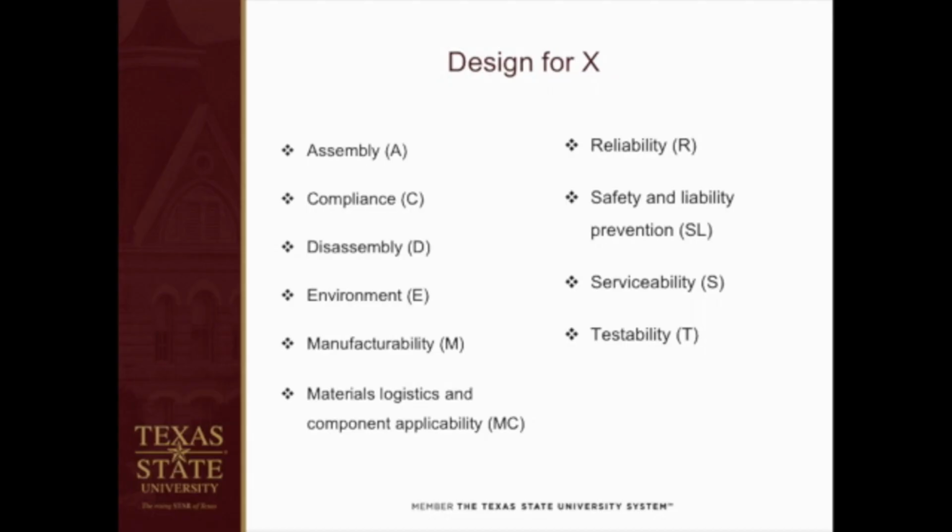Now think about manufacturability. What does that mean? It means that certain things are okay from a design standpoint, from a functional standpoint, but trying to make the stuff would be very difficult. Maybe you need a casting process, but the metal may have a high melting point. That means it's very difficult to melt the metal, and it doesn't pour well into a mold. Or two pieces of metal may not weld very well together. So thinking about how good it is in terms of being able to machine it, weld it, cast it during the design stage, those guidelines are called design for manufacture.